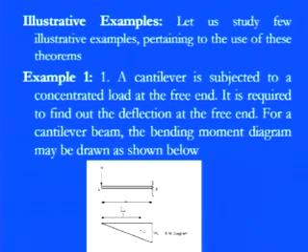So you see here, this was a pretty special case when the point of contraflexure was there, and in that case we are dividing the beam into two different segments, the positive as well as the negative bending moment, because we are simply focusing on the bending moment diagram. So when we have a positive bending moment diagram and a negative bending moment diagram, then we need to consider accordingly, and we need to incorporate those sign conventions in calculation of the slope as well as the deflection.